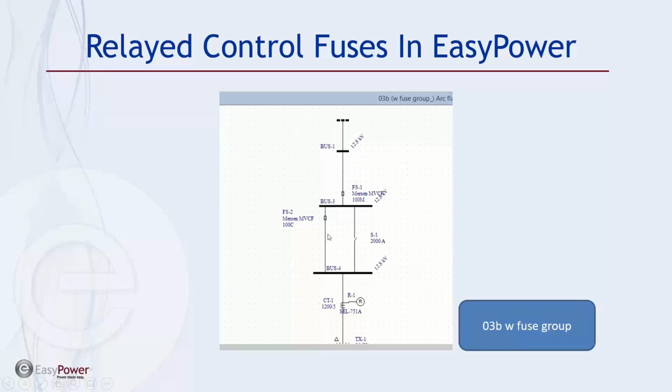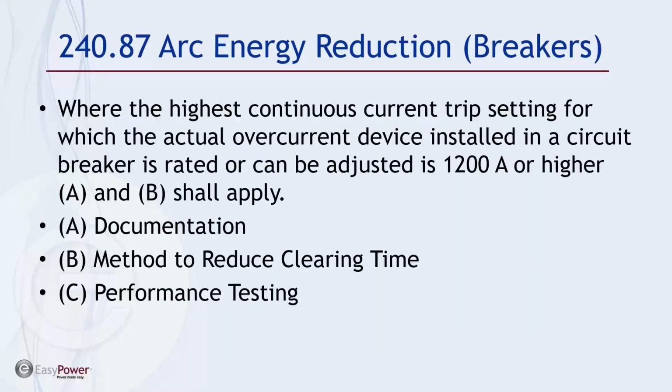The alternative is to put these in series, open up the switch and not have the delay of a current limiting fuse. At any rate, the different pieces of hardware are just now coming out. EasyPower can include in the library, and would be more than happy to specialize or detail any particular TCC curves that are included. It's just a matter of requesting the model be set up.